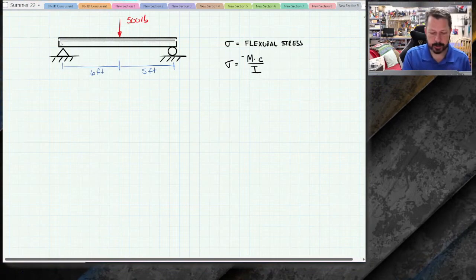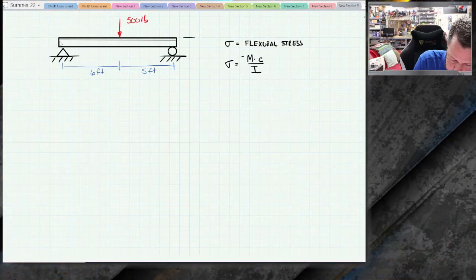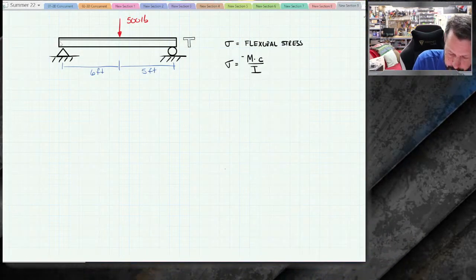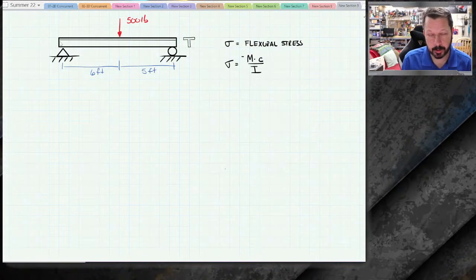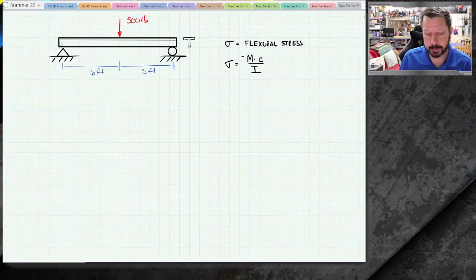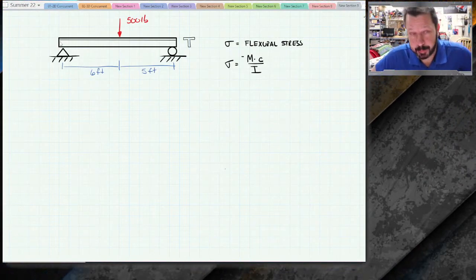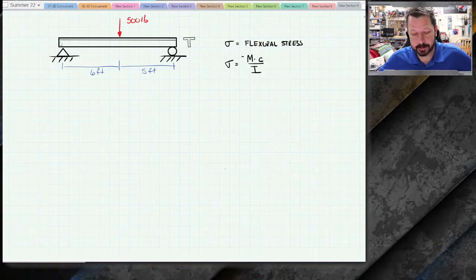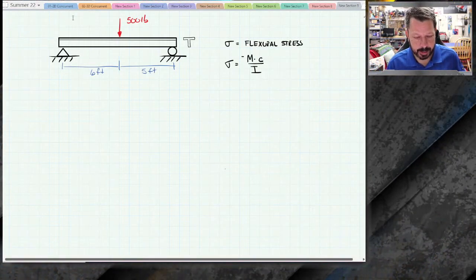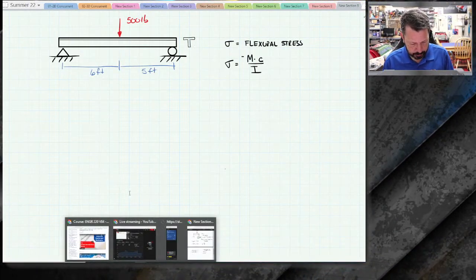So that's showing the cross-section of this thing. So it's a T-beam. Or it might be a WT beam, W meaning wide flange T-beam. So if we can find information about a particular wide flange T-beam, then we can just look up the value of I. To do that, we need some charts.